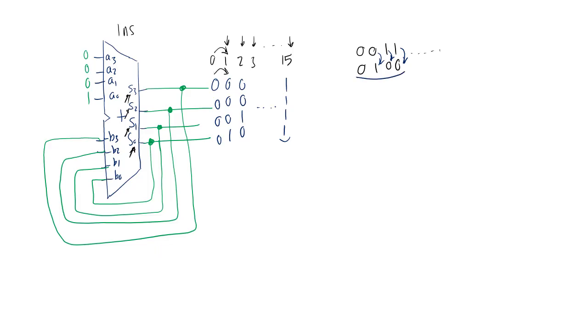And if one of them is happening in 500 picoseconds, the other one in 600 picoseconds, and the other one at 1 nanosecond, then for every 2 transitions of the first bit, I'm going to have 1 transition of the second bit. And the delays might actually be that different.